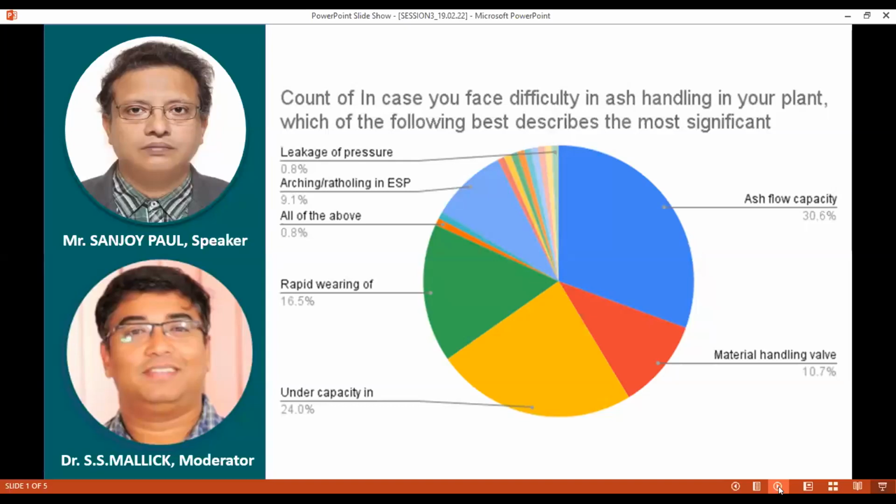sometimes by heating. When we are providing fluidizing air, it is hot, and when the ash is coming, it is hot. But while flowing and coming in contact with the cold pipe during the rainy season, the temperature drops. So intermittently, some heating arrangement is to be provided so that the moisture does not get precipitated, and the temperature stays above the dew point and flow is proper.